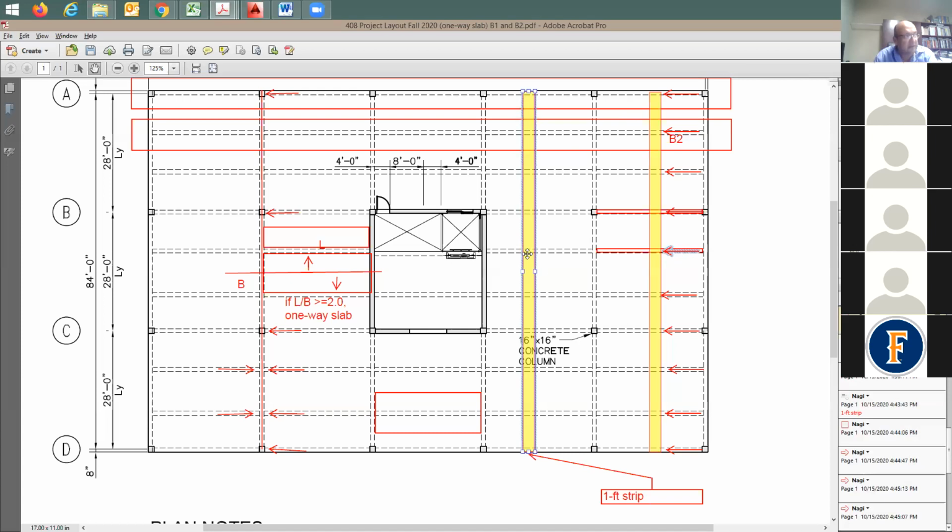Someone's going to say, how about in this case? Because look what happened. All of a sudden, the beam is not continuous. Which beam? I'm talking about the slab, but when I do the analysis, it's going to be like a beam. What is the reason? Because the number of spans is different. In here, I have 9 spans. In here, I have 1, 2, 3, 4, 5. And what's happening here on the top? This is going to be a separate beam, and we have only 3 spans. How about in here? This is going to be exactly the same as this. There's no difference because I don't have any interruptions. All the spans are the same, right?